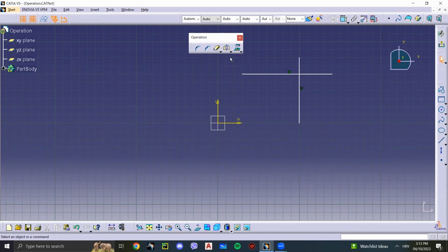What you need is to select the elements you want to be mirrored, then the reference point or line. I always use a construction line or axis line to use as our reference point. Now, let's say we want this on the other side of this line. We can mirror it by selecting mirror. Select the set of elements to be duplicated by symmetry. Let's take these ones. Now, select the line or axis from which the elements will remain equidistant. There we go. That's it.